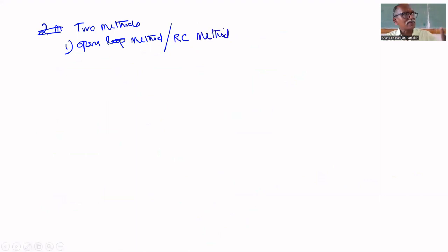You obtained the reaction curve in the level process. In open loop, you gave a 5% change at the nominal level. Nominal level means the level at which you always want to control. You got an S curve for that open loop change. It looks like an S, that's why it is called an S curve. This curve is called a reaction curve. That's why this method is called the open loop method or reaction curve method. So for level process, we will use the open loop method or reaction curve method.